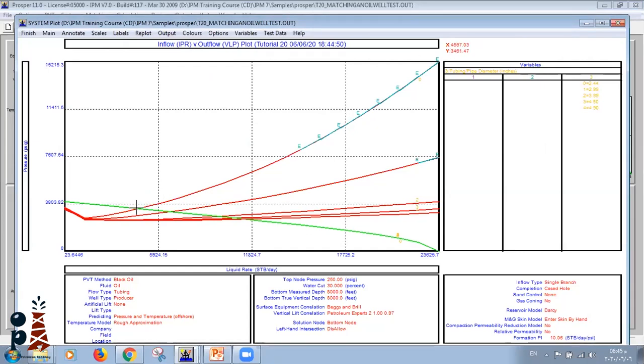So this is the number 0. It is the smaller tubing size. We will see we have a rate around 4,600. Then using higher, bigger tubing means I have a bigger rate. And as we see, then using bigger and bigger, there is not that much effect on the gain of the production. So always, or most of the time, we are doing a compromise here.